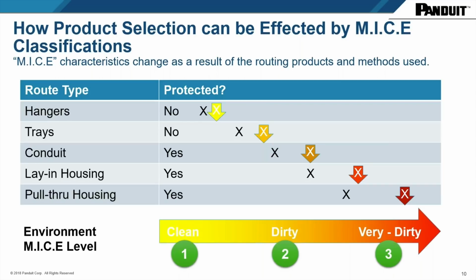So how do we protect our cables? If you put your cable inside of a conduit system, then you're basically changing what you call a commercial grade type cable. If you put it inside of a conduit, you give it an additional protection so it can take a dirtier environment because the conduit is protecting it.